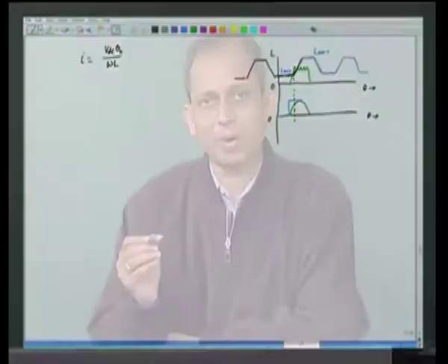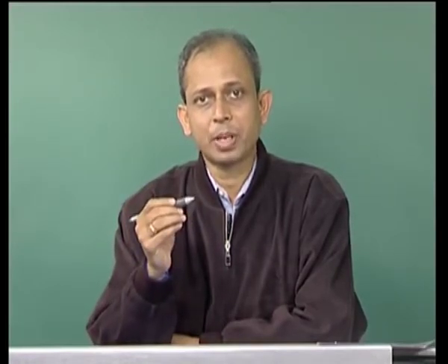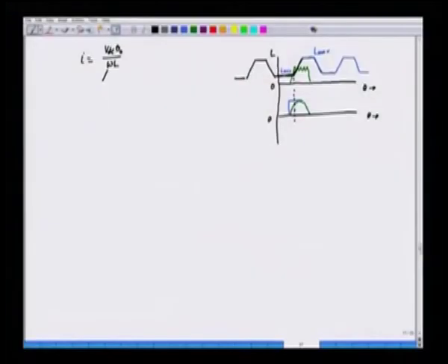So, we can control this advance angle. So, this theta naught is increased in such a way that the current rises quickly during this L minimum, and with the increase of speed, when the speed increases, we increase theta naught in such a way that current is still maintained. So, what we can do here is that we can have another situation. This is our advance angle here, theta naught.